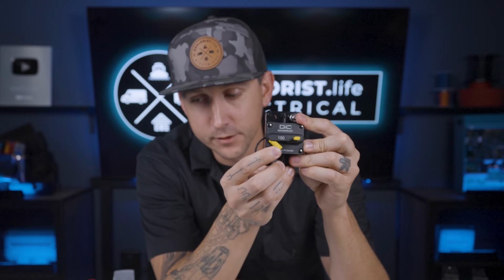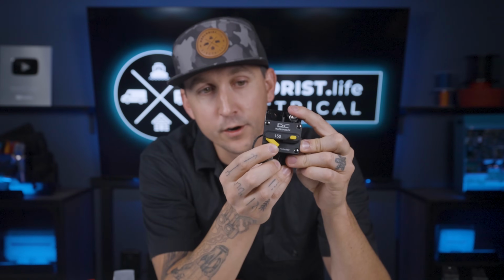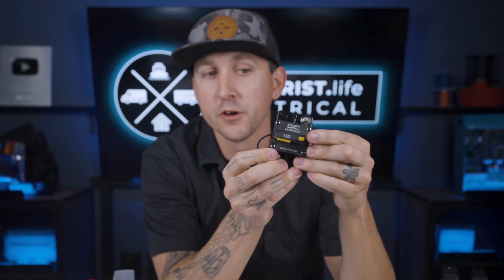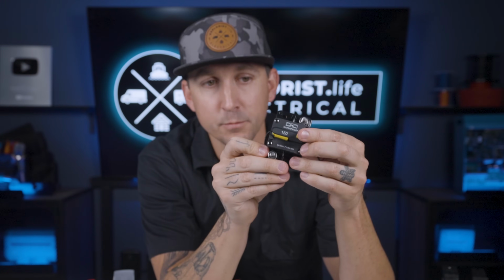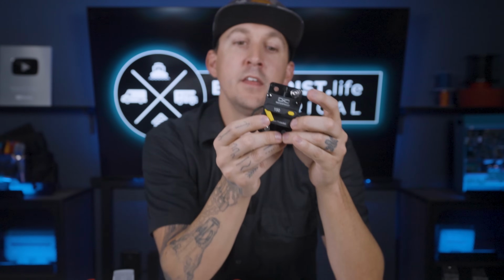Or if there is actually a problem, whether you've overloaded the circuit or there's a short circuit, which is flowing too much power, that arm is going to be tripped by the internal mechanism without obviously having to push that button, and that's going to indicate that the circuit is blown. And then you can further investigate for a short circuit, or if you've plugged in way too many blenders to the circuit or whatever device you've plugged in, you just unplug those and then reset the circuit, and then don't plug in quite as much next time because that's going to overload the circuit every single time.